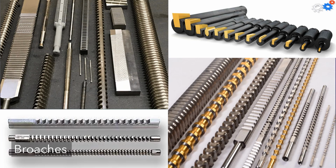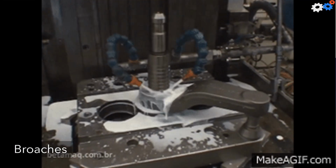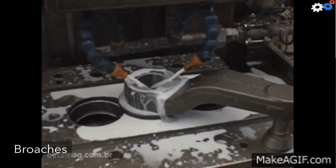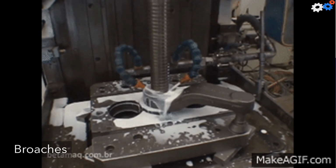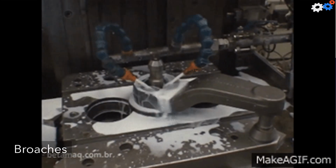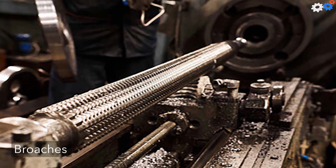The broach consists of a series of distinct cutting teeth along its length. The feed is accomplished by the increased step between the successive teeth on the broach. This feeding action is unique among the machining operations because most operations accomplish the feeding by a relative feed motion that is carried out by either the tool or the work. The shape of the cut surface is determined by the contour of the cutting edges of the broach, particularly the final cutting edges.